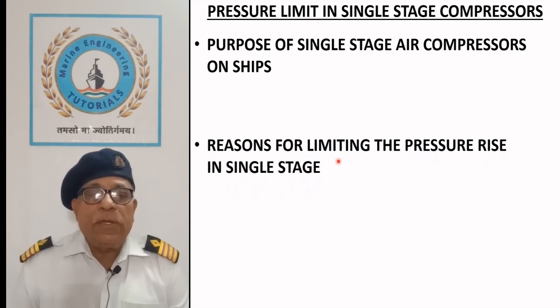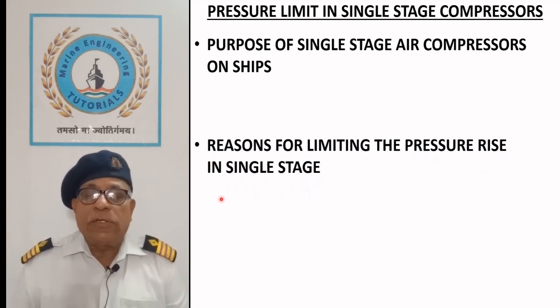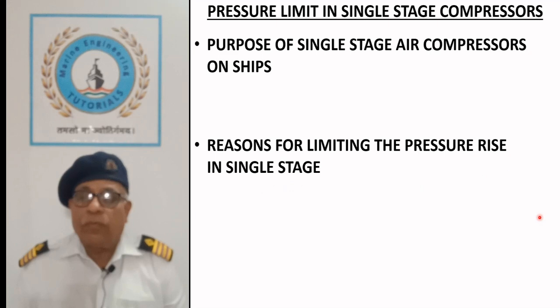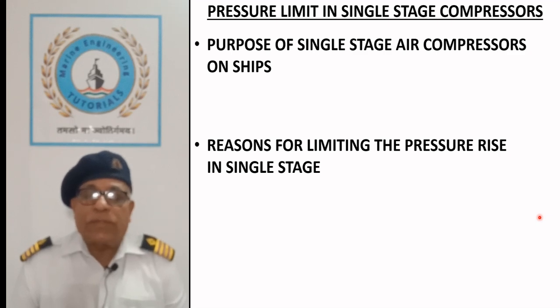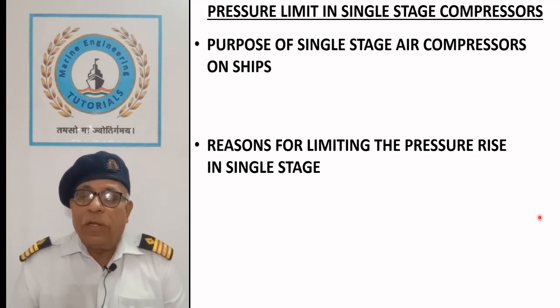Reasons for limiting the pressure rise in single stage. The reason for limiting the pressure on air compressors working with single stage is to prevent the explosion in the cylinder due to ignition of vaporized lubricating oil, similar to diesel engines.